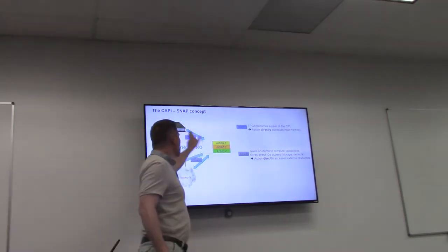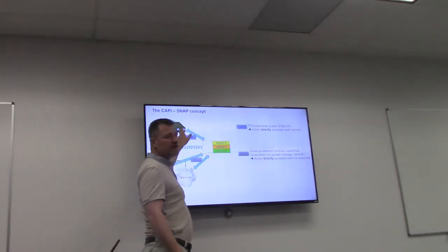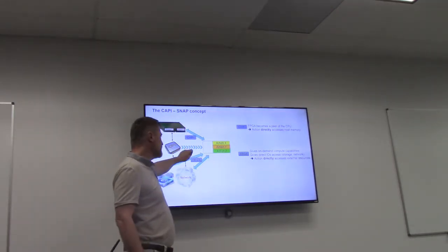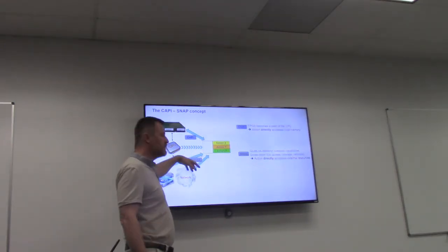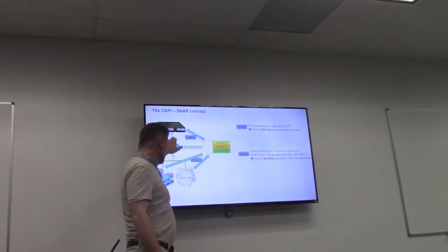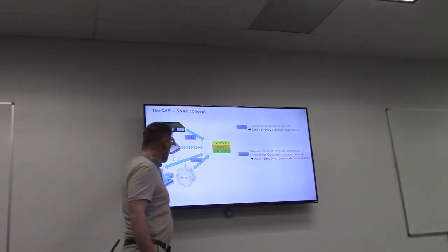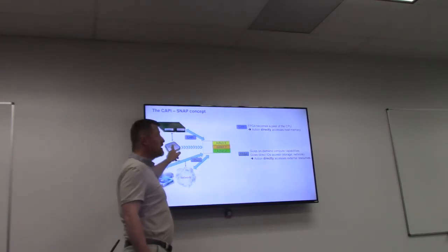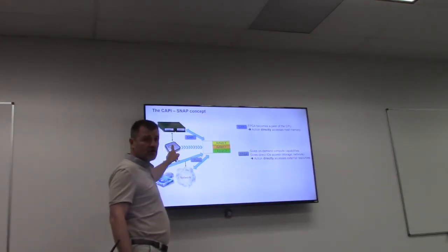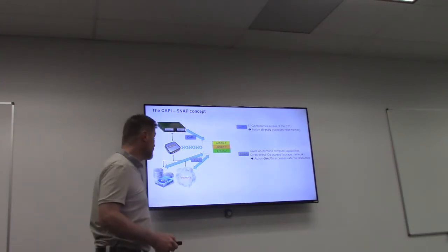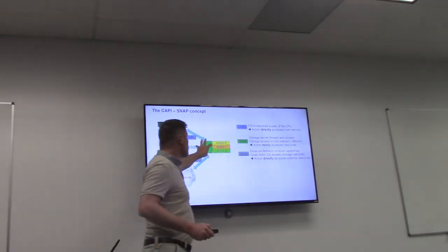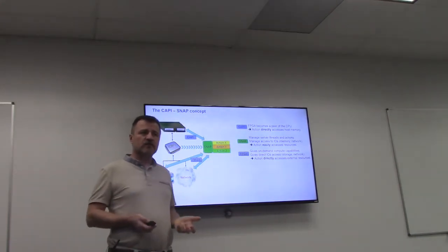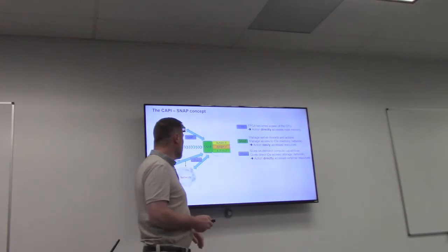CAPI is providing a very fast link, and this fast link includes coherency to the memory. So it's very important. I cannot go into the details, but please ask questions on the side. I can give you my name. CAPI is a very good technology because the hardware inside will allow the FPGA to talk directly with the same address as your program is talking. So no conversion. It's all handled by hardware. So it's very fast. SNAP is the logic and the environment that we offer on GitHub for you to make all this work.